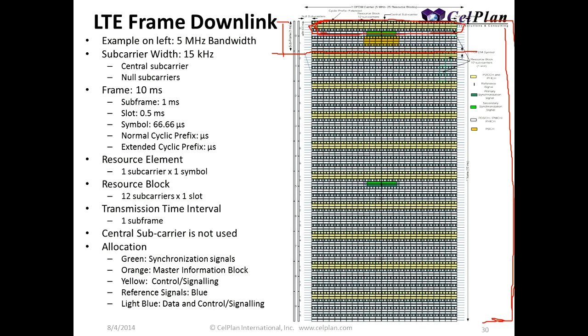So the UE will get this information, think, okay, I have this slot to send, and it waits the 4 frames and sends it then. So it's very important to understand the concept of TTI, and that the mapping is done by the eNodeB for the uplink and downlink. Of course the downlink data is sent in the same TTI, but the uplink data will be sent 4 TTIs later.